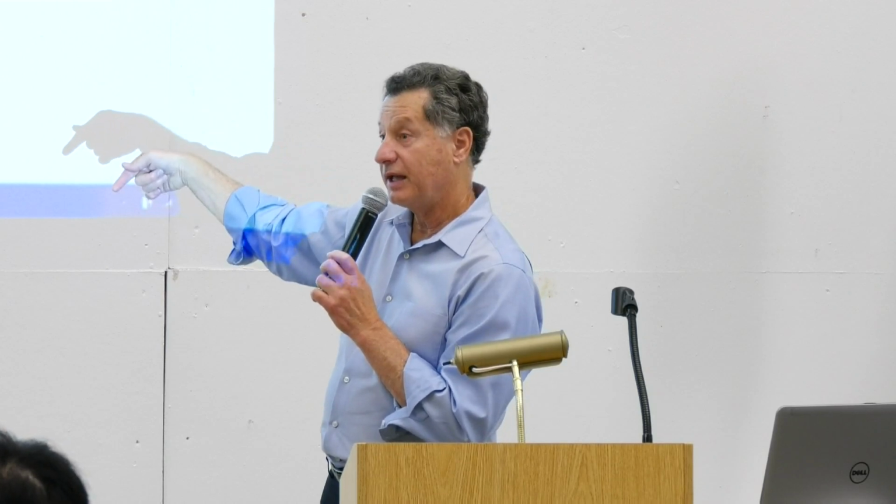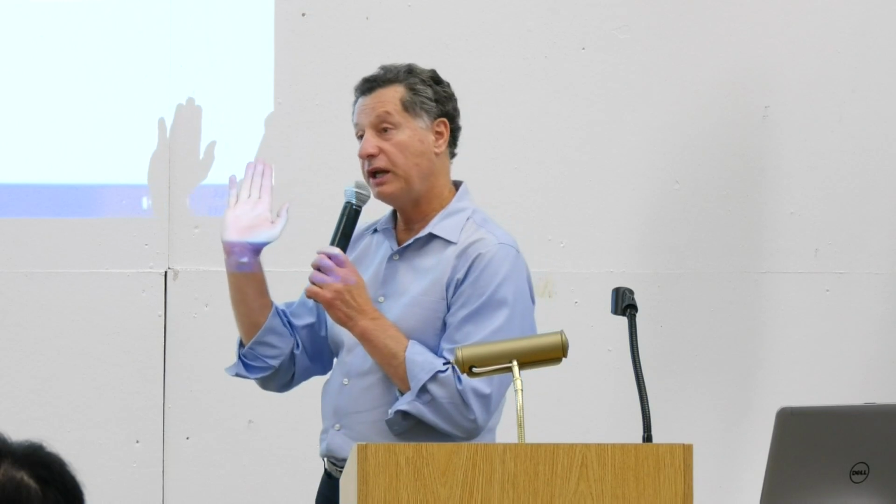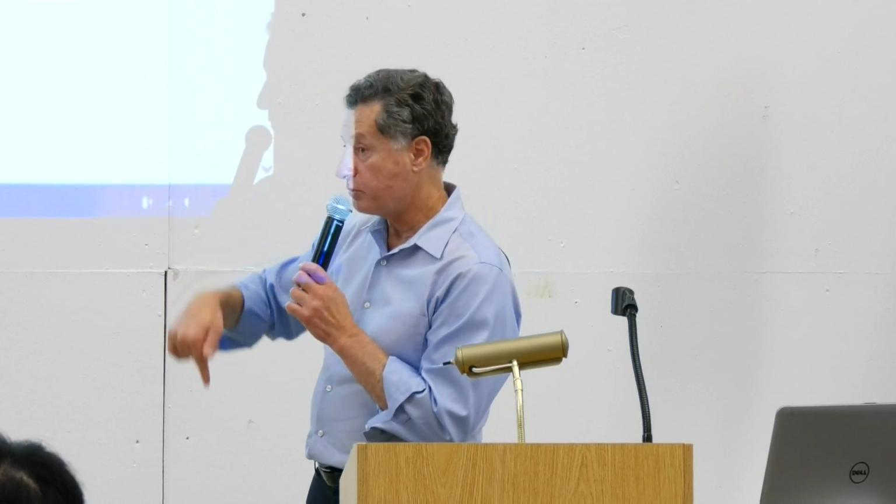Okay, so if one module is up like this and the sun's shining this way, what happens to the module behind it? It gets shaded. Shading is no good. The further you tilt them up to get more production, the more they'll shade each other. And if they shade each other, it drops their production. So you have to separate the rows to account for that inter-row shading, and then the fewer modules you can pack in there. So there's a big trade-off about how you're going to pack them in and how much they're going to produce.